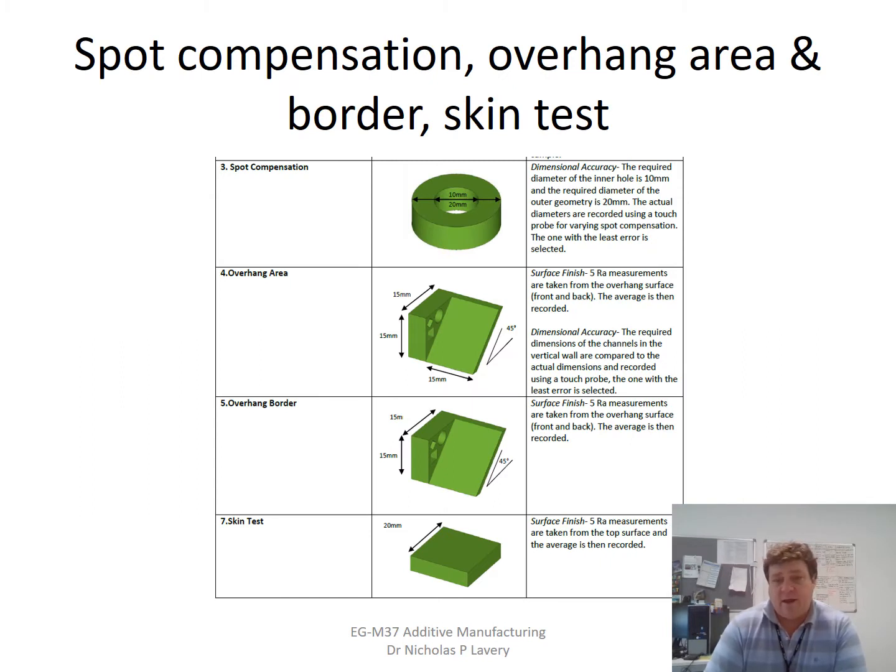You might have an annulus form like that, to test the overhanging area and the capability of the overhanging area, particularly from the perspective of what happens to the surface roughness as the critical angle is tried. You can see various shapes which will be testing the level of accuracy of the build in a vertical direction, and these can then be checked with a backlight system.